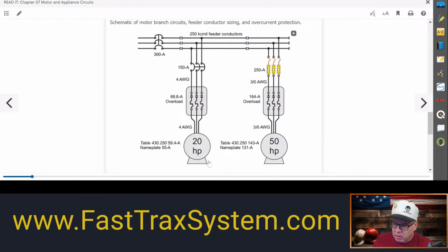And then we need to know what the motor's FLC is. When we see FLC, there's another slang term that we use, and that is FLA. FLA, just think of that as the amps on the nameplate. FLA is nameplate amps, versus FLC, which is what's in the NEC. Why do we always use the FLC for most of the stuff, like the wire sizing and short circuit ground fault protection? Because the FLC is a fixed number.